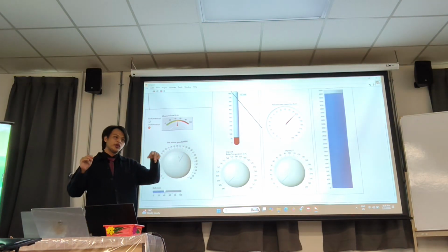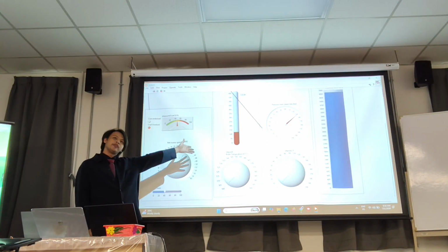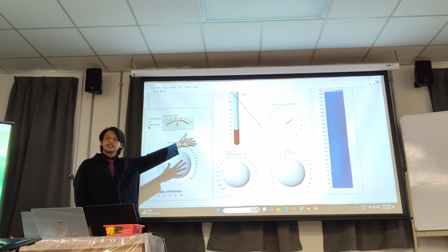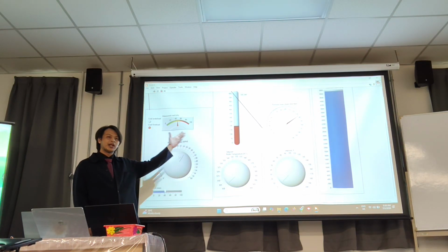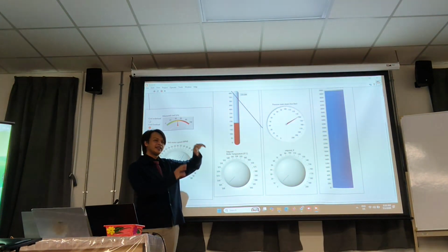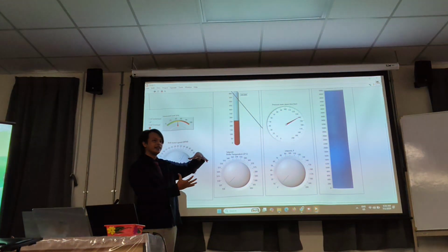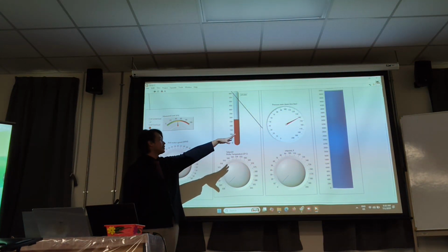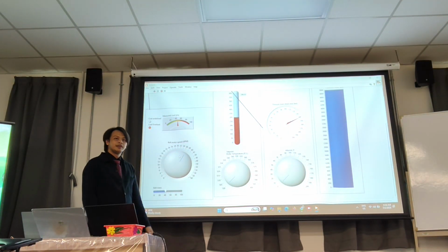So now some of you might wonder, if the furnace is not blasted up, if the coal didn't enter the furnace, how can there be pressure? That is what I mean by these are two separated loops. They are not integrated. Supposedly they should be integrated, so that the pressure can also react to the mass flow of the coal itself.